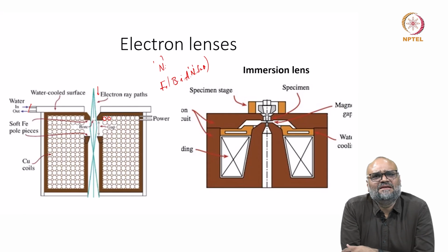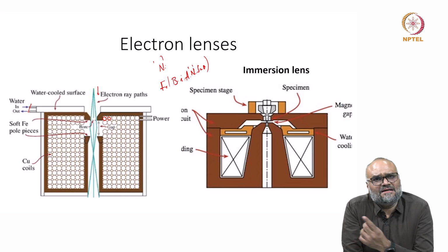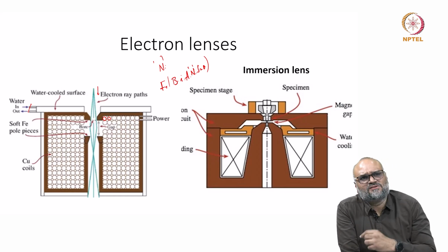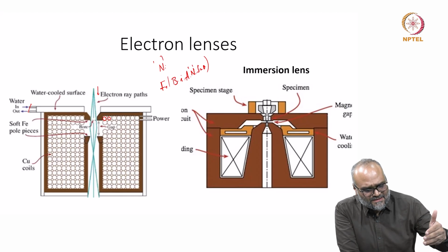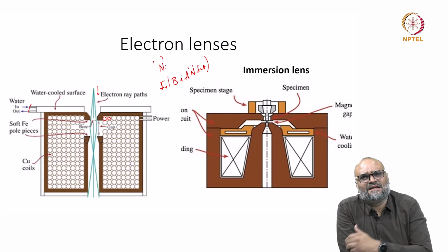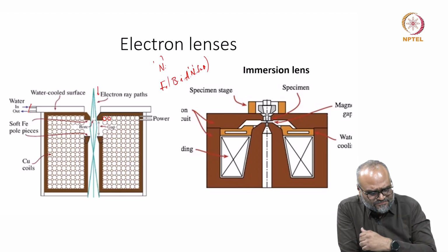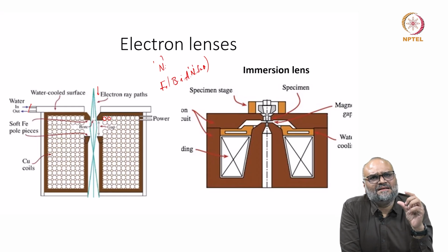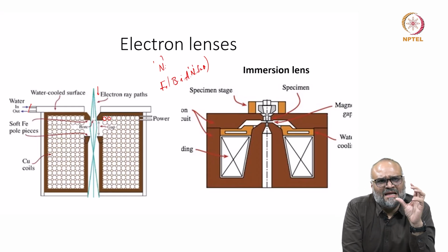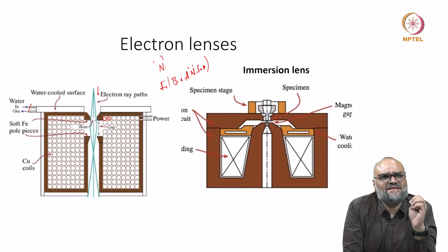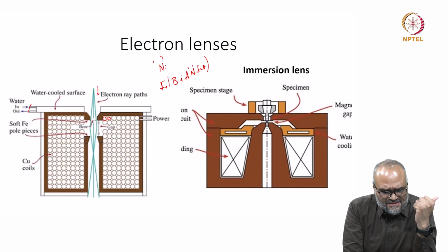If you remember the lab layout and the demonstration video that I showed you, there's a chiller which is used to circulate the DI water through the microscope to cool these electromagnetic lenses at various locations. Unless you're maintaining the entire microscope column at an ambient temperature, you would have several problems. One of them is the thermal drift as well.